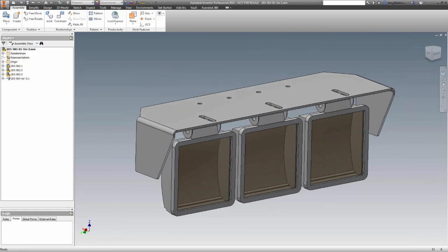If I look at the Vault browser, I use this as a way of interacting. I get symbols indicating the state of the file. So at the moment this file is checked out to me, but no changes have been made, so it's actually in sync with the server. As soon as I save it, it'll go out of sync, and when I check it back in, it'll go back into sync again. So what I'm going to do within here is